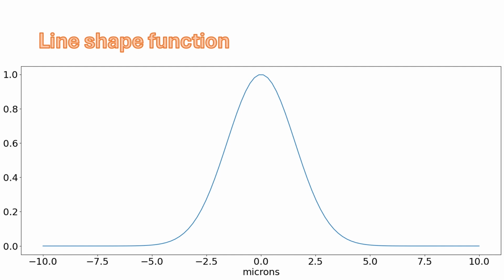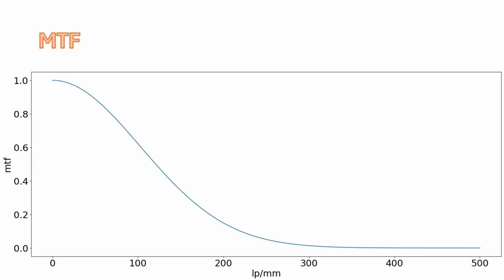We get the horizontal data in microns because our native sampling is in pixels, but in this case we know that the pixel pitch of the sensor is 1 micron, but the pixel pitch of the sampling is 2 microns because we're only looking at one of the color channels, which is sampling every other pixel. Then we take the Fourier transform of this, which in the case of the ERF just means plotting with the known exponential, the variance function we got for the exponential, and we get this. And so Nyquist for this